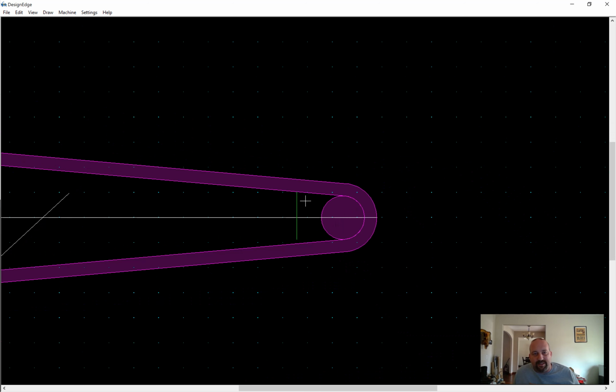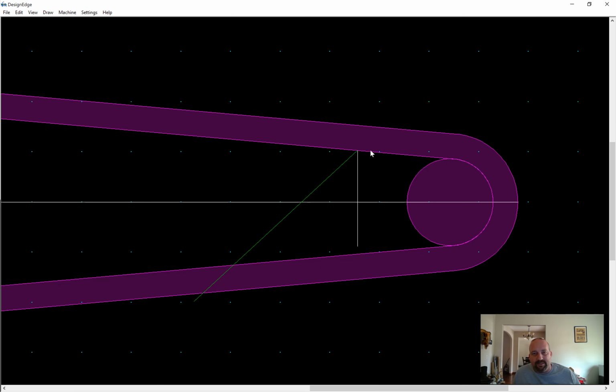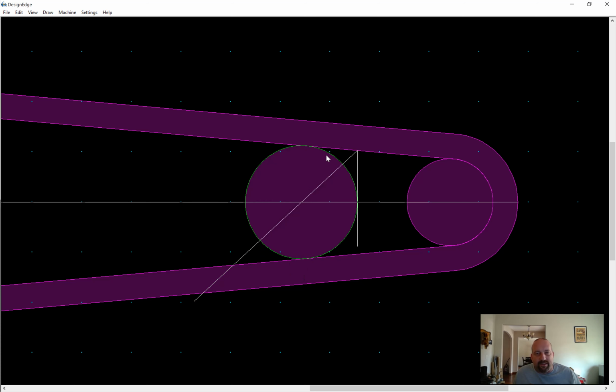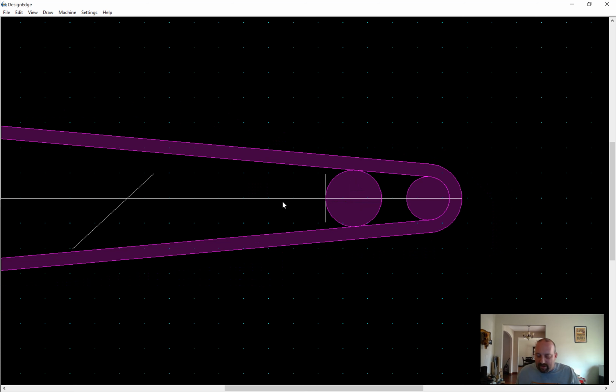So I'm going to X extend that up there. Then I'm going to get my angle back over here again. I'm going to C copy from the E end point to this E end point. And wherever that angled line that bisects it cuts that orthogonal line to make that next radius is correct. So I can Q from I intersection to I intersection, and there is a tangential circle. So I'll delete that out of the way, and I can just M move, M midpoint, I intersection. It'll pop it right there, offset 1 enter. That pops it over an inch for me.